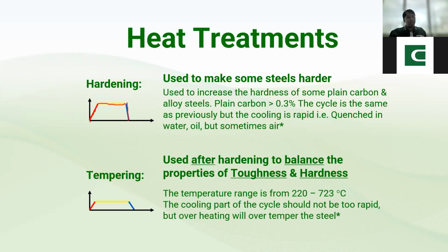But by practice, ang pina-follow ko mga 450 or 400 degrees centigrade in order for you to have a maximum balance of toughness and hardness. So we have 3 or 4 heat treatments: annealing, which creates ductility; normalizing, toughness of your material; and the hardening or quenching, hardness of your material. If you want to balance between toughness and hardness, that's tempering.